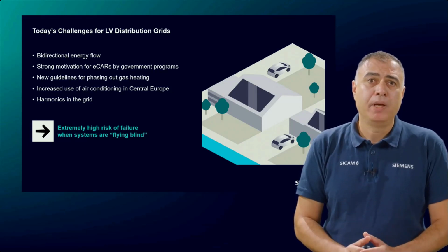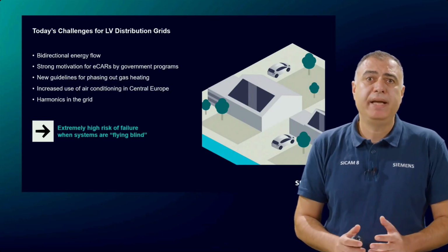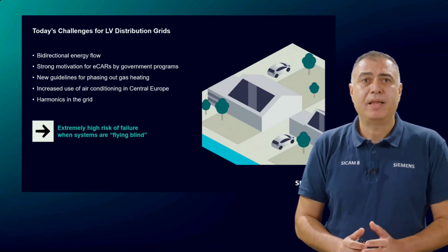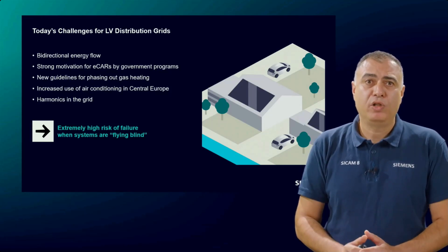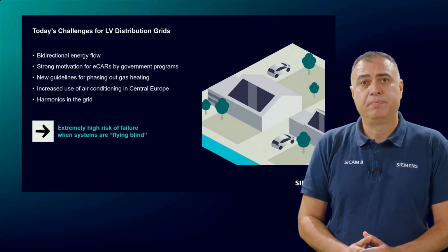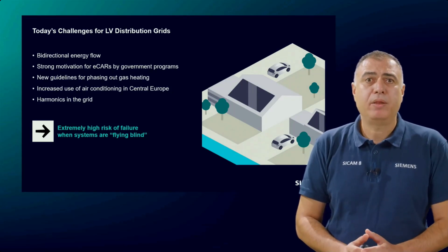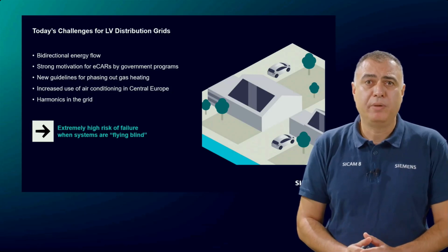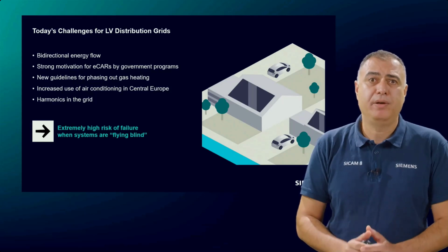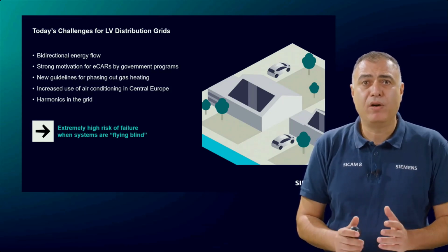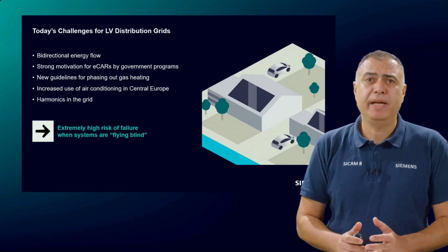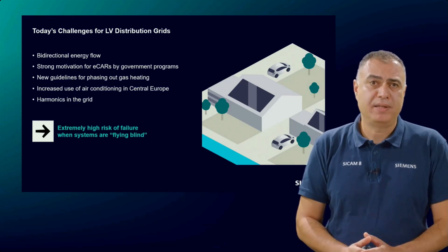As mentioned before, typical low voltage transformers mitigate the negative impacts on the medium voltage network. This means that only monitoring the medium voltage will not help you to detect possible challenges on the low voltage side. Please also keep in mind that the primary equipment of the low voltage distribution grids usually has a lifespan from 30 to 50 years. This means that many of these power grids are based on primary equipment that have been selected according to obsolete load profiles.